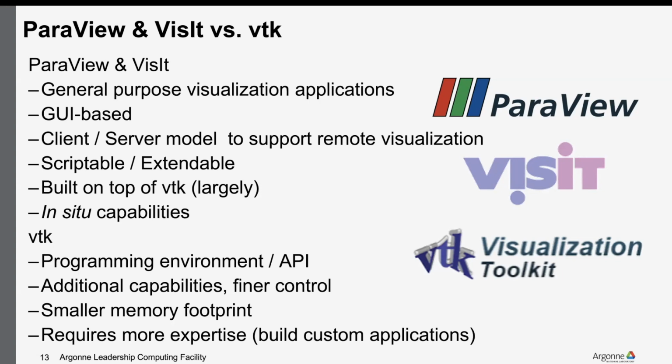They're both scriptable and extendable. Our team has built plugins for ParaView, for example, for reading specific types of data sets that weren't initially supported. Scriptable in that they both have a Python interface. Largely what we tend to do is build up our pipeline using the GUI, and then we can save that as a Python script that we can then run in batch mode and generate animations and series of images, rather than have to be connected and have a human in the loop while it's doing that compute.